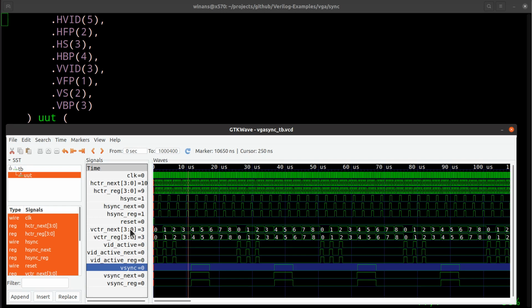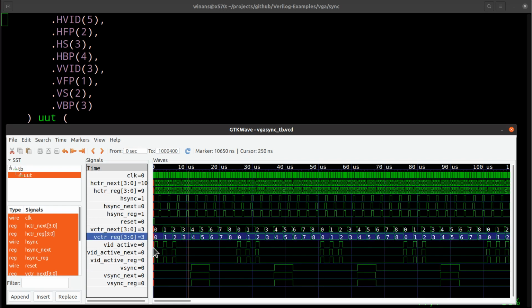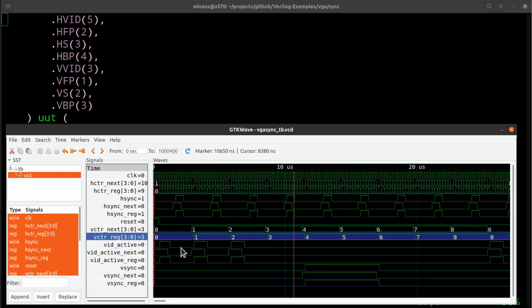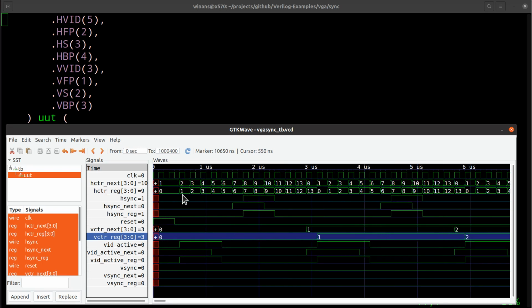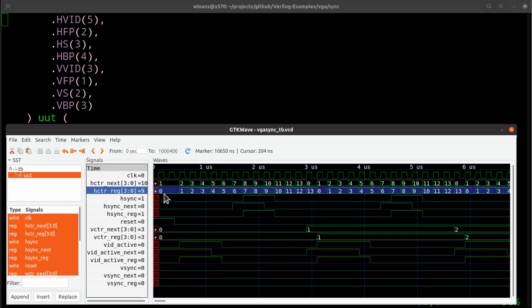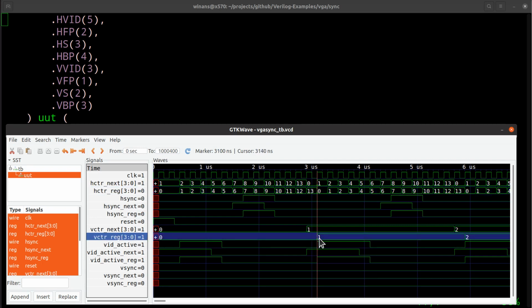And you can see that because of the vertical counter register. It holds the row number, 0, 1, 2, and so on. We can see that this thing advances at the right time. I think we already saw that. Whenever the horizontal counter goes from the max value back to 0, we should see this increase. The vertical counter goes from 0 to 1 every time the row wraps around. So that's happening. Okay, now what else do we got?